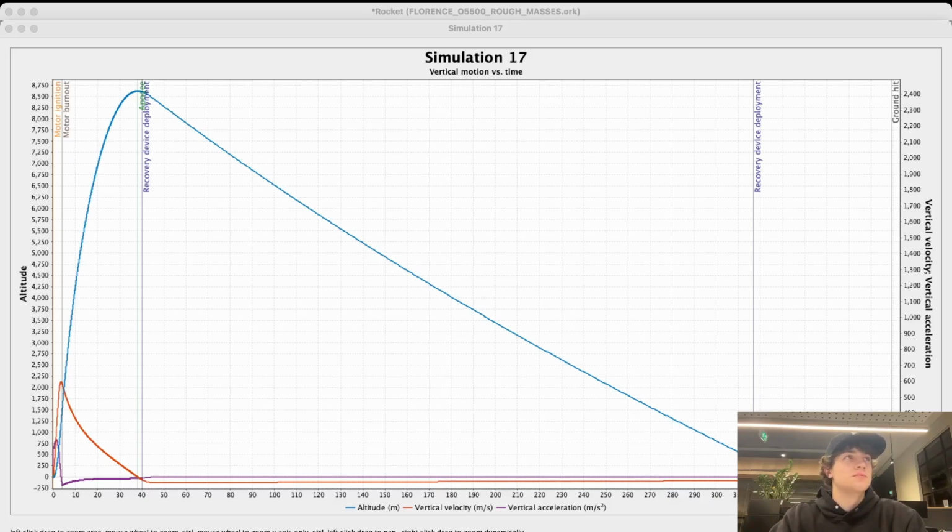The way that buffer is set, so essentially the way the motors work, is after they burn out, they'll set off, I've explained this already, I think, sorry to repeat myself, a fuse, which will, once burnt all the way through, set off a black powder charge, which will pop your nose cone. You can cut that fuse and make it a bit shorter.